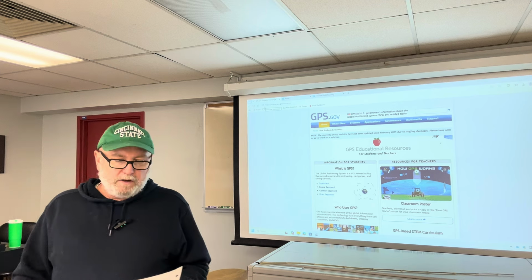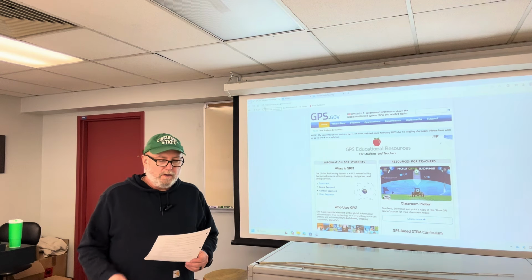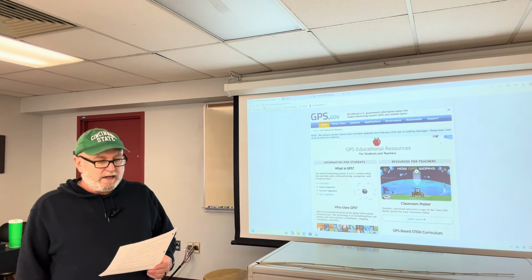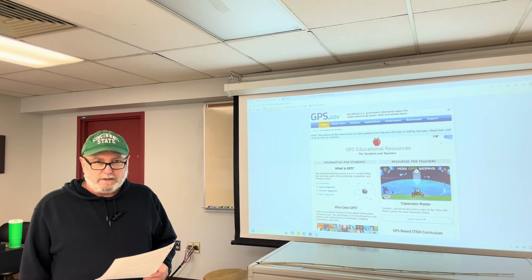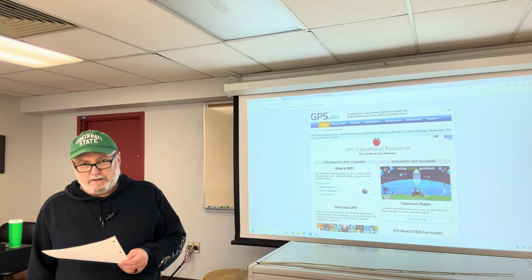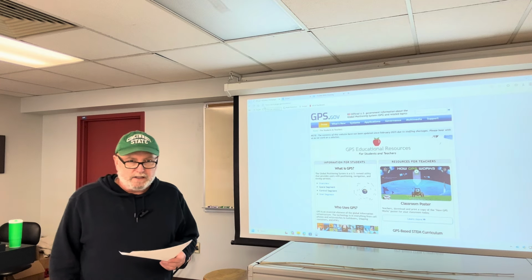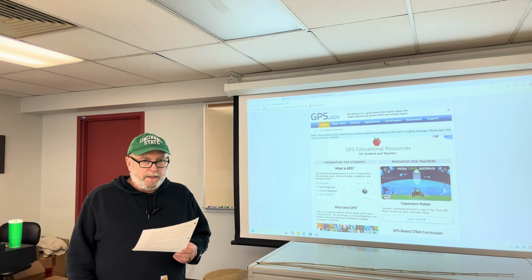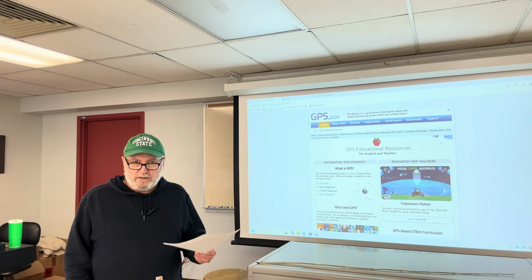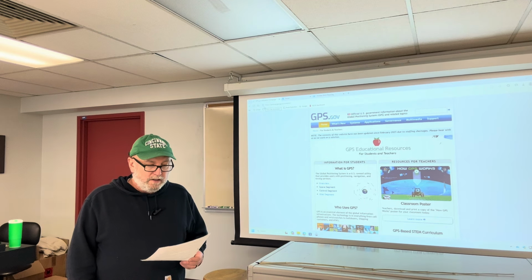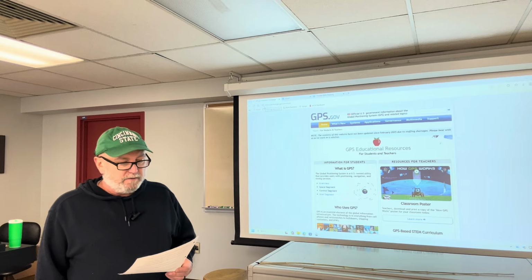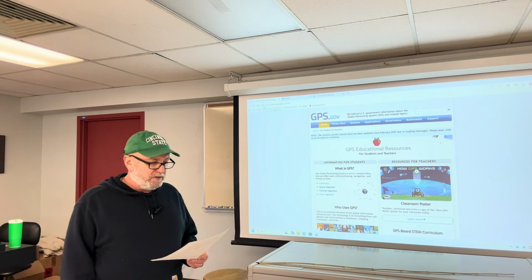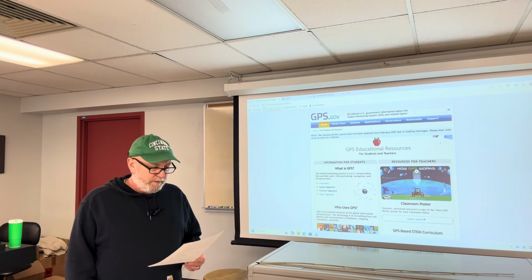For most of the survey work that you do, you're going to want to watch the PDOP, HDOP, and VDOP. These are factors when you're specifically looking at the planning, you can see this. Anything that's a factor less than 2 is considered good or excellent. Anything between 2 and 4 is good, 4 and 6 marginal, and above 6 is poor.